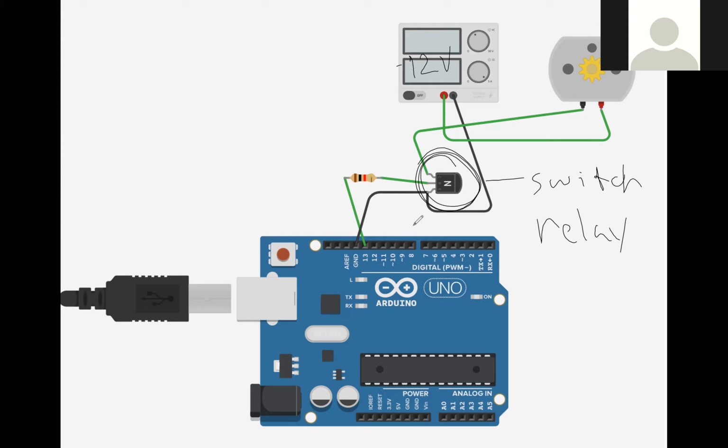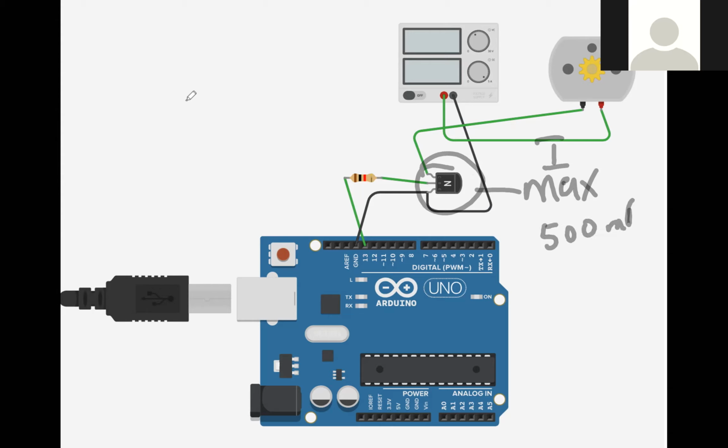What you're seeing here is one very common use of a transistor. Now I do need to be completely honest here. I am glossing over one fact that, if you know a lot about transistors, you might say, hey, wait a minute, Mr. Hendricks, you're leaving out something very important. Transistors also have a maximum current that is allowed, and it varies from transistor to transistor. Some transistors, the most you're allowed is maybe 500 milliamps. If you try to exceed that, you're going to burn out the transistor.